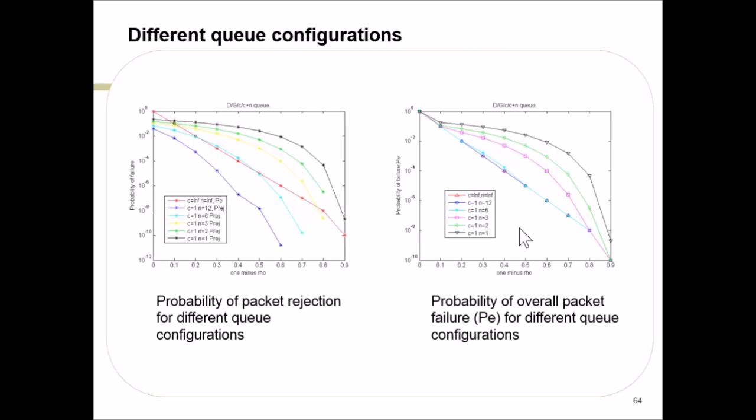Even in the 802.11n standard, most of my PhD work was on the wireless decoders for 802.11n and WiMAX. So the packet sizes are different. For WiMAX, the packet size could go up to 2304 bits, and it could start from around 300 bits or so. The rate also could be from 0.75 to 0.8.